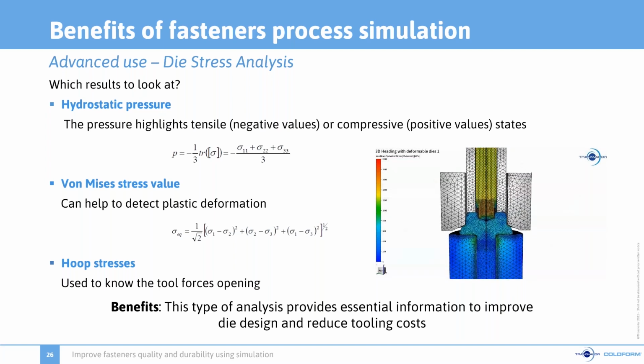The advantage of performing a fully coupled die stress analysis is that all interaction between the workpiece and the tooling is calculated at any time step of the computation. Therefore, temperature, deflection, or stress variation occurring on the dies are accurately modeled.